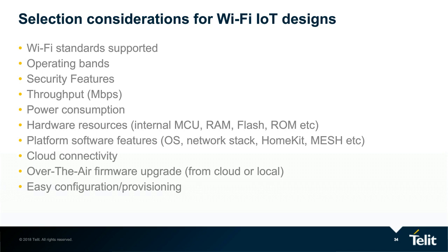Now, coming to power consumption, it's one of the very interesting topics. As you know, unlike the other short-range technologies, Wi-Fi provides wireless connectivity for both low and high bandwidth applications. This means that it supports various data rates, modulation techniques, and extended range. Some of this makes the radio pretty complex, and that results in increased power consumption. So to make Wi-Fi viable for battery-operated low-power devices, various power-saving schemes have been implemented in both the SoC and software, apart from the standard IEEE protocol, which is governed by 802.11. These system power-saving schemes are vendor-specific, but made sure to be interoperable with other devices in the network.